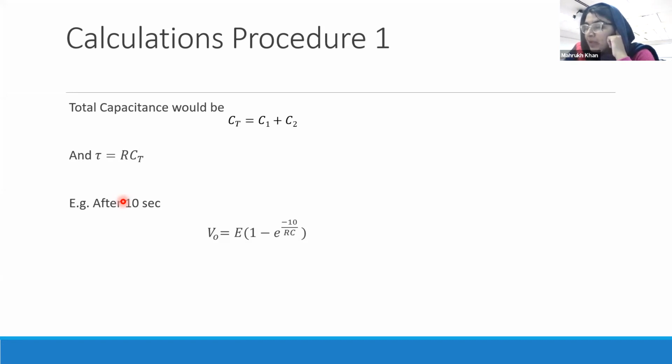So someone says 20 seconds is your 1 tau. So what should your 5 tau be? What should be the value of 5 tau? 100 seconds. 100 seconds. So if you see the graph, it is up to 200 seconds. So you can point out that at 100 seconds, it reaches its maximum value.